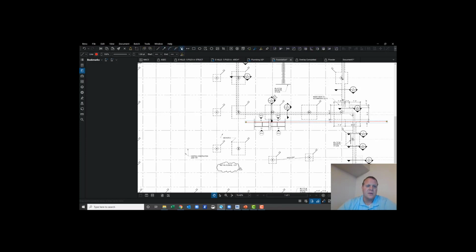Let's just imagine for a second you have a big spoil pile right here, and they're excavating this and dropping their spoils right over the top of your footings and foundation that just got poured. Or what if they're not poured yet and you need to be working concurrently together and you've got a bunch of spoil piles there? So we're talking about coordination and construction sequence, and it's not just the components that work, but thinking through that logistical thing as well, and it's super important.